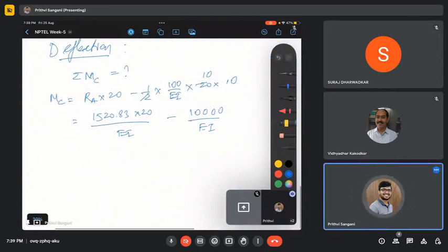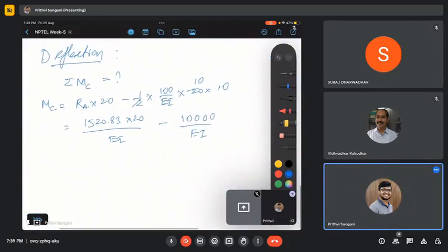So 3000, this is 10, so this will be 10,000, so this will be 30,000 and something else. So 30,000 and something, or minus 10,000, that should be 20,416.67 by EI. Okay. So you remember this, if the shear force is positive, then the slope is anti-clockwise.